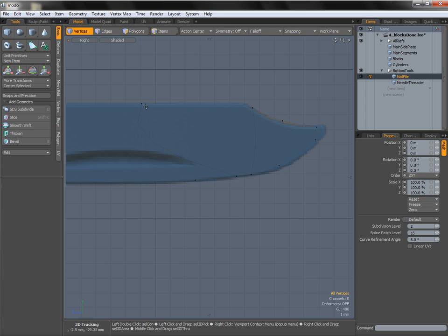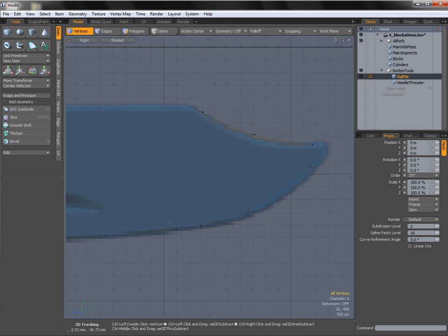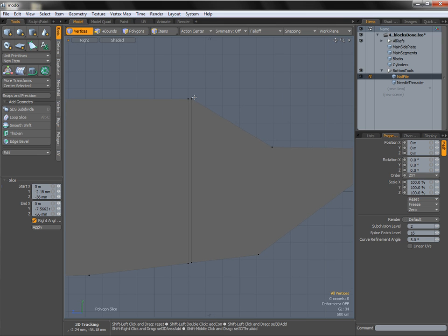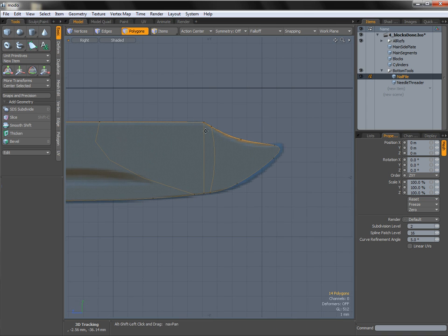I'm going to zoom out ever so slightly, and then go into tab mode. You see that the edge we just added in is now being moved to the left, but this one is now being pulled ever so slightly to the right instead. So it's being pulled towards these guys. As you may have guessed, we need to add an extra edge to the right of it to make sure it doesn't move left or right and stays exactly on that corner. Again, using the slice tool, which is Shift C, add in an extra edge down the bottom. Then if we go back to tab mode, you'll see, if I double click the polygons, that we've got this nice corner there now. We've got this vert staying exactly where we want it. And with that done, that's all we're going to do for that one.